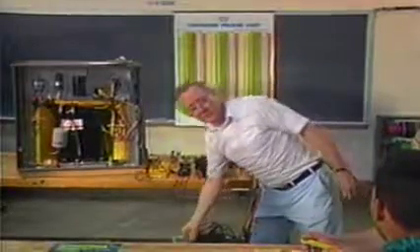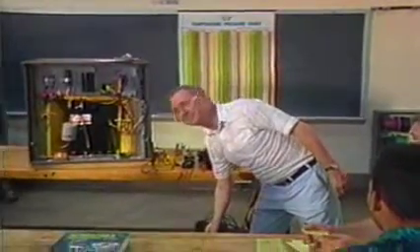Are there any questions? Jack? Can you always tell the refrigerant temperature if you know the pressure? Yes, Jack, as long as you know what the refrigerant is, the identity of the refrigerant, and as long as the refrigerant is standing static in a cylinder, such as in storage, or it's boiling in an evaporator, such as in an operating air conditioning system, or if it is condensing in the condenser in an operating condensing system in an air conditioning system. Are there any other questions?